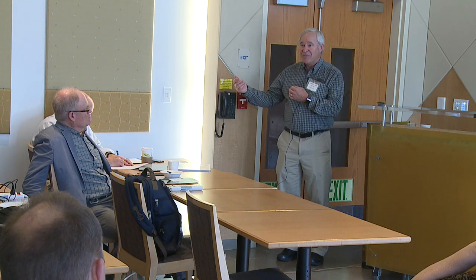So we do what we can psychrometrically to just avoid humidity sensors. And by the way, on the economizer one, in the study that we did that came up with all these set points, you can get it off our website. The article is called "Why Enthalpy Economizers Don't Work." In that, we did all these simulations and showed that the dry bulb ones, if you get the set point right, work almost as well as the differential enthalpy anyway, within a couple of percent. And that's if the enthalpy ones actually worked, which they don't. So there's not too many reasons to use a humidity sensor.